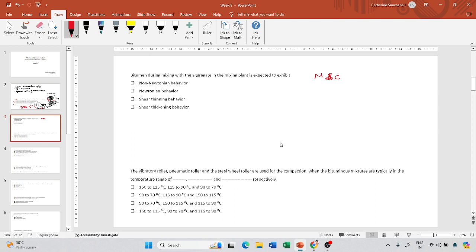Now see, in the case of cement, let us take concrete. There also the binder is your cement. And how will you get workability of the cement? You add water to it, right? And you will get the required workability, plus aggregates. So the workability is determined in terms of the water to cement ratio, right?